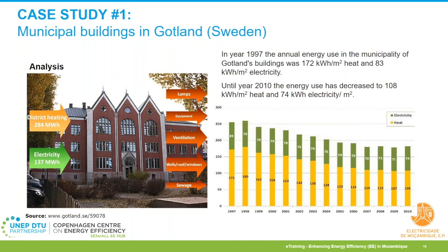And the measures that were undertaken were that, for instance, the existing equipment or systems were optimized in all buildings in order to have every building operated as close to optimal as possible while maintaining comfort, of course. So things such as indoor temperatures, operation hours of different systems, night reduction of indoor temperatures and lights were adjusted and monitored in order to optimize demand or the use of energy. Other measures were improved routines concerning management and monitoring in order to make equipment for heating and cooling, ventilation, and water supply work in its most effective mode.